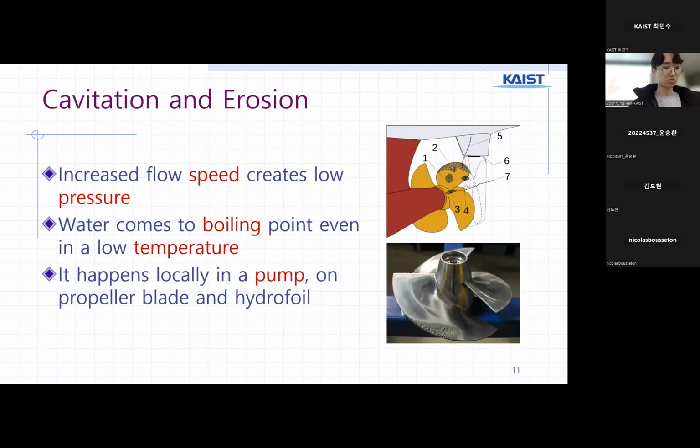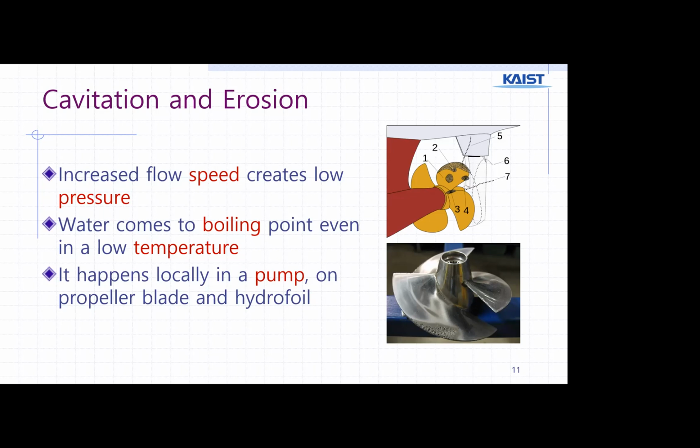Now let's look into cavitation and explosion in propellers. As the flow speed increases, it creates a low pressure zone. This phenomenon causes water to reach its boiling point even at a relatively low temperature. It occurs locally in a pump, on propeller blades, and hydrofoils.